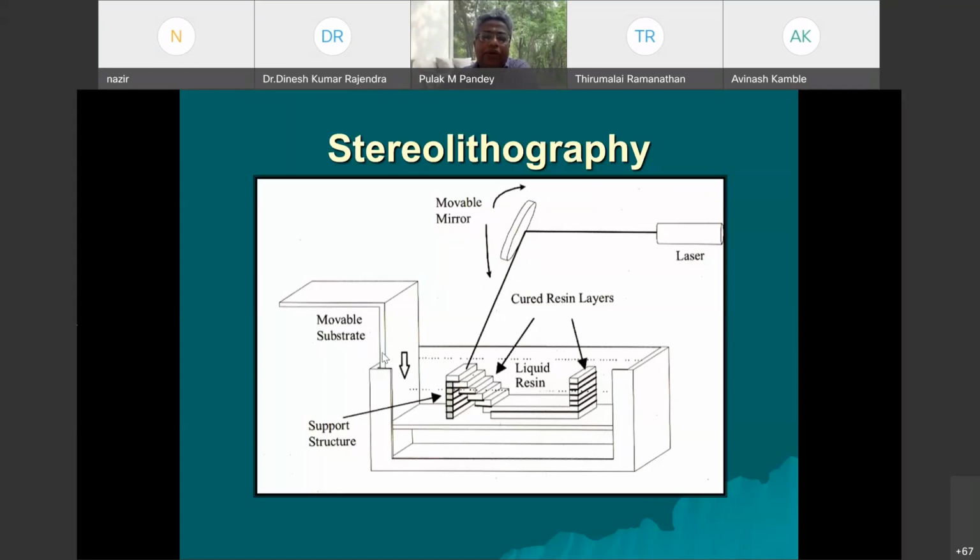And what we do, we pour photosensitive resin. So there are photocurable resins. They are basically monomers in the language of chemistry. So they are liquid monomers and their property is such that if light above a certain threshold frequency falls on this liquid, there is free radical formation and these radicals start connecting with the neighboring radicals and they form very long chain molecules, which is nothing but a polymer. This is known as the photopolymerization reaction.